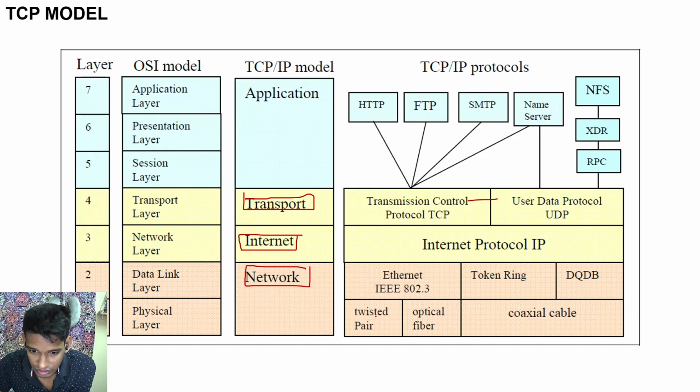So basically, the twisted pair configuration, the optical fiber SFP ports that we use, and the coaxial pair configuration all come in the physical layer. What we have discussed was twisted pair serial communication. The optical fiber can also be used for serial communication using light modulation techniques, which can be covered in a later section. And the coaxial cable can also be used for serial communication. What we have discussed up to this point was in the physical layer, and Modbus was in the data link layer, and Ethernet is another important protocol.